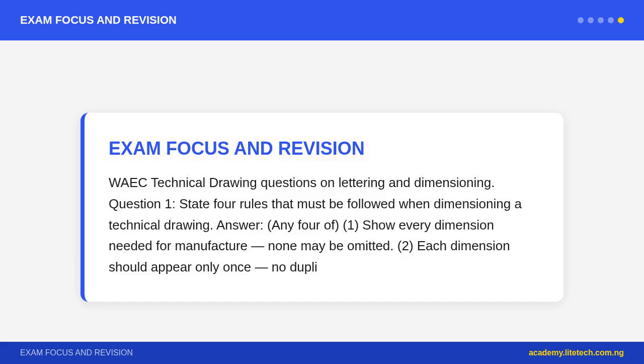Question 4. What information should a title block on a technical drawing contain? Answer. Title or component name, drawing number, scale, date of drawing, name of drafter, name of checker or approver, material specification, surface finish, sheet size, company or organization name. Some title blocks also include revision history and projection symbol, first or third angle.